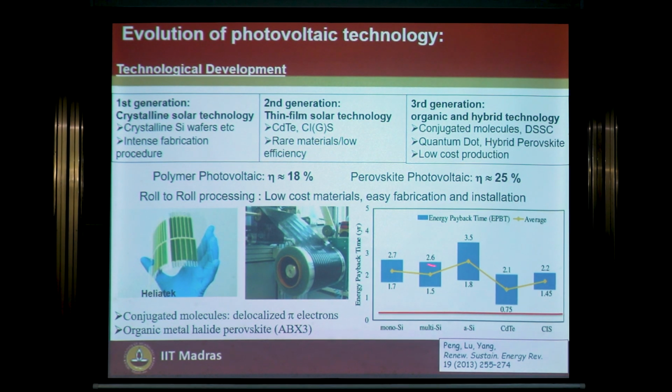As the sir was asking, what is the energy payback time for any technology in any energy source? When we talk about the energy payback time, it basically says how much energy you have put in by building or starting the system, and how long it takes to give back the same amount of energy. So if you look into that, silicon comes in the range of about 1.5, considering different aspects, going all the way up to 3 years.